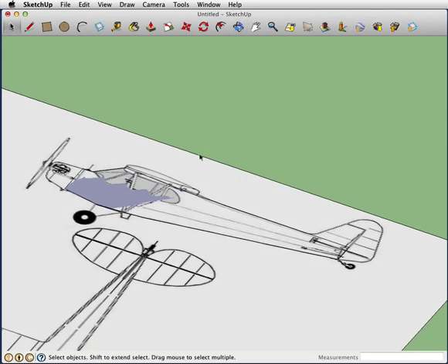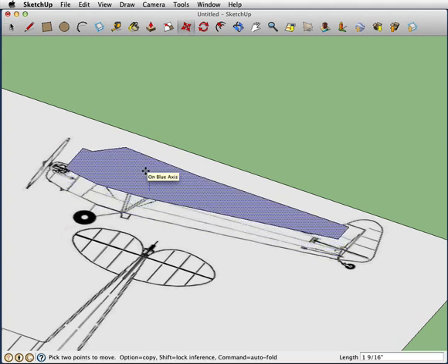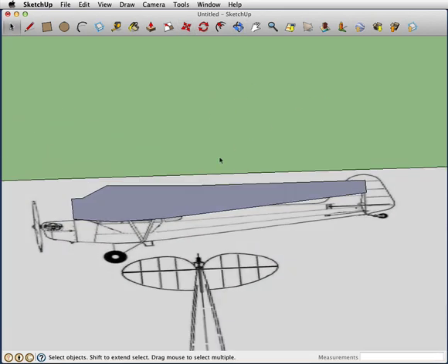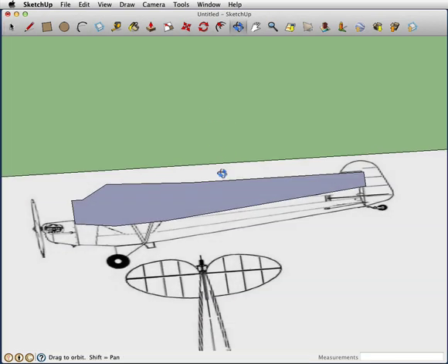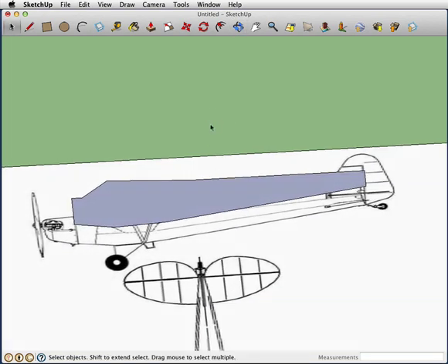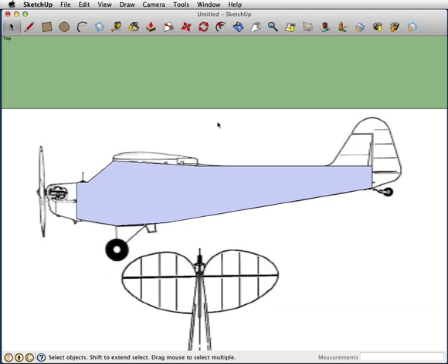So we're just going to float this geometry up above our reference geometry just a bit. I'm going to select it, take my move tool, and move it up along the blue axis just a little bit, so that now it sits above our reference material and they're not intersecting each other. I'm going to switch back to my top view with Command or Control 1.